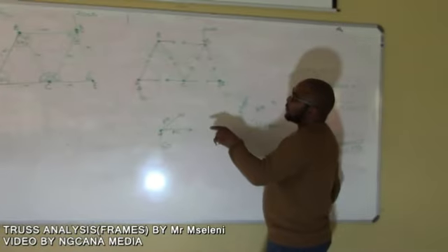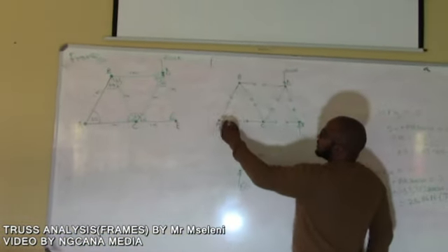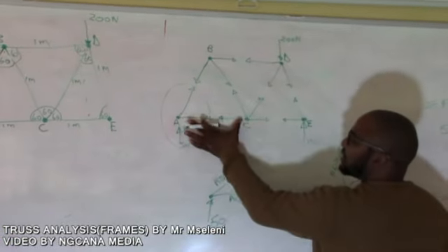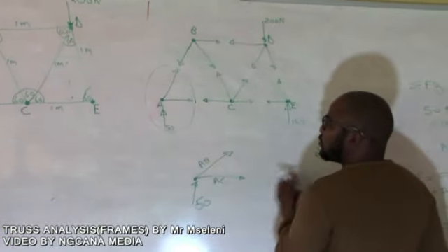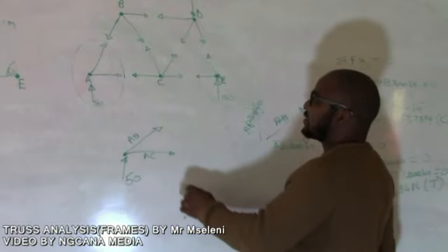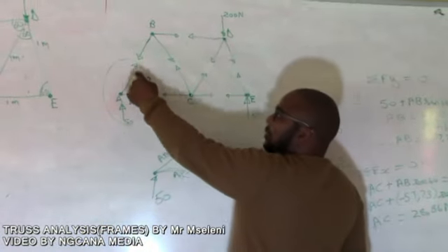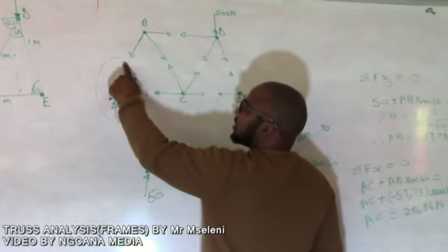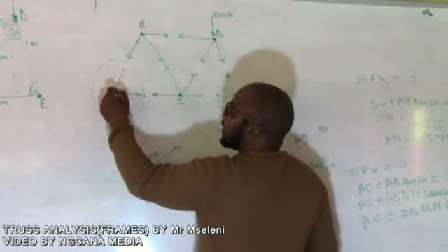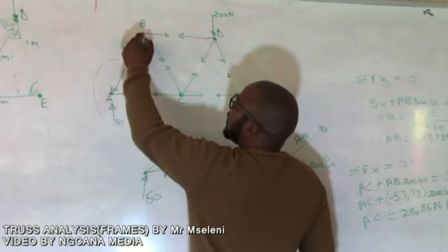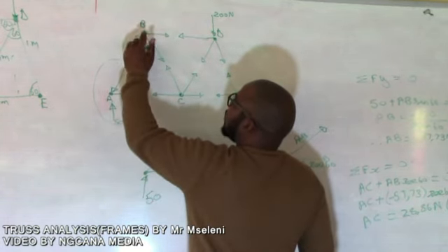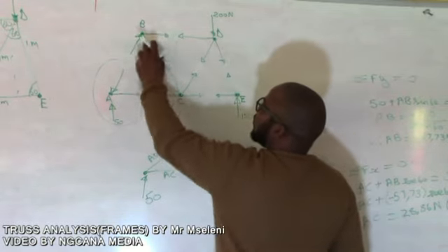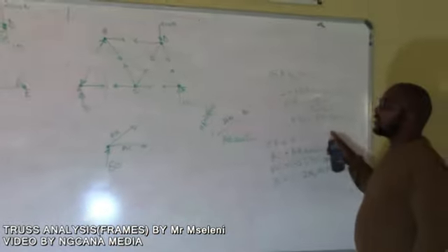This is what I normally do. It simply means that this direction is okay, meaning this member AC feels 28.86 in a tension direction, but this one is in compression. So what you normally do is change your sign after you're done, and then you put your magnitude on, with the sense of the feeling on this member, compression, because it simply shows you there.